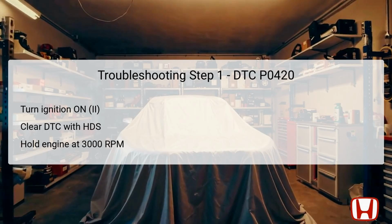Next, proceed to a test drive under specified conditions, such as maintaining certain vehicle speeds for an extended duration, as outlined in the diagnostic text. Monitoring the OBD, onboard diagnostics, status during this phase will help gather critical data on the catalytic converter's performance.